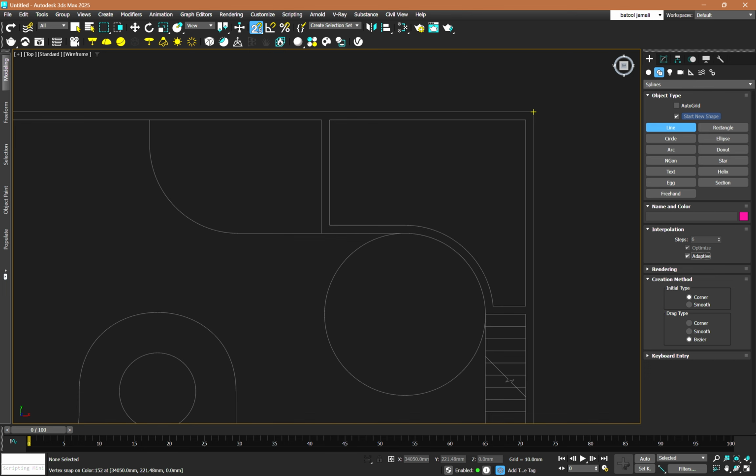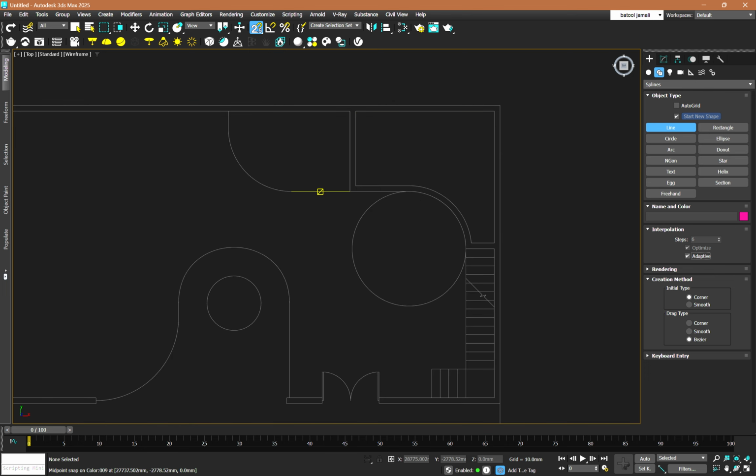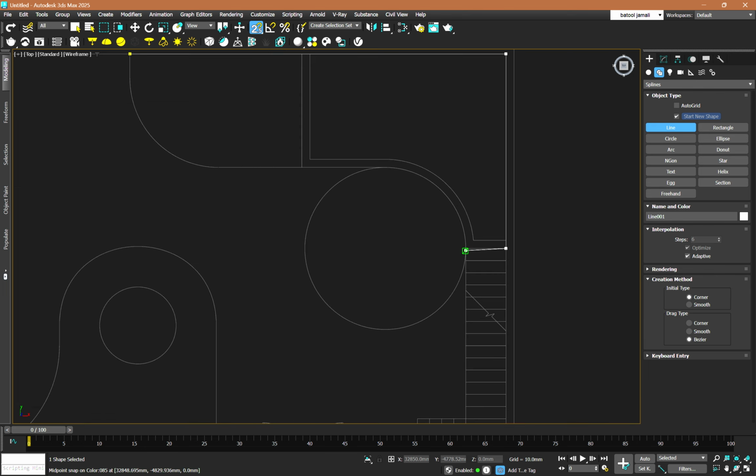And now I'm going to start drawing. Now make sure that it will only snap. You need to make sure that when you are snapping, you're getting the point that you want. So if I click here, for example, I can, but I cannot click straight up here because I don't have any point to click to. Okay, so let's say I'm creating the slab. So I will click here, and here. Now I do have a curve.